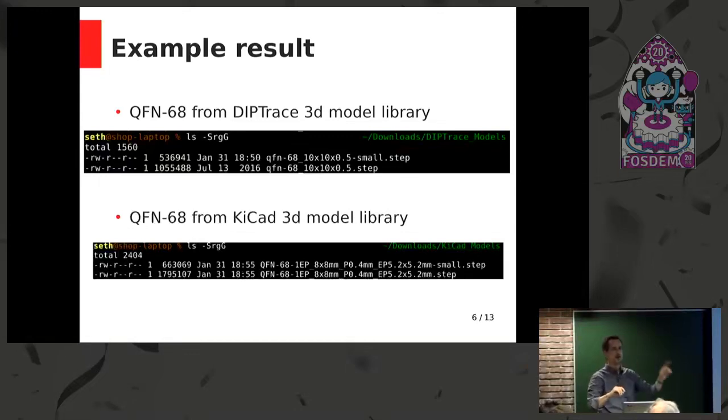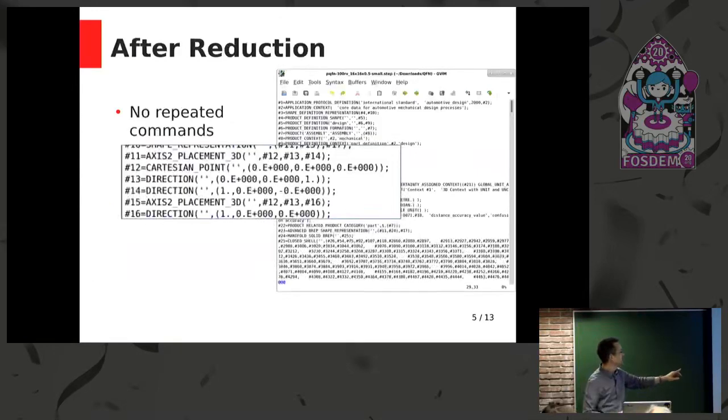What we're doing is we're saying we don't need the same information in multiple places in the step file, and step supports this natively. So we're not creating a different file format. We're just creating a step file format that is actually slightly more optimal. Critically, we leave a few cases of duplication in there, where you might be able to reduce it further if you wanted to. You might notice here that element 14 is the same element as element 16.